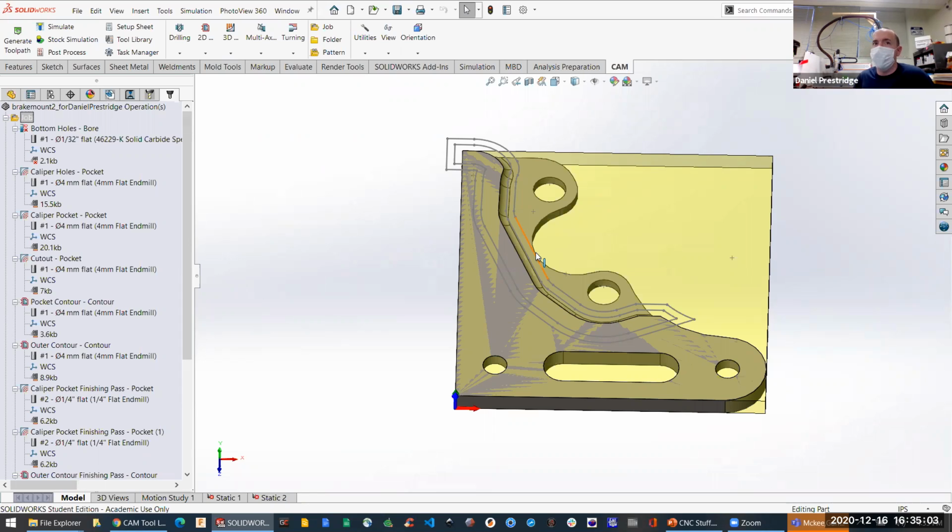Fortunately, the HDPE doesn't absorb moisture the same way that MDF does, which is medium density fiberboard. That's a common spoil board that people use. If you run a bunch of your codes over the course of several days, maybe you're using coolant, it can soak into there, swell up, and now you have a Z height difference that you weren't expecting. So you might dig further down into the piece, or it might not get to it, like anything could happen.